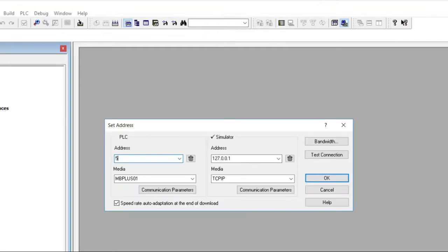If your PLC on the serial network is at node 4 or node 1 or however it is, usually your engineering workstation will take the address number 0 or 1, depending on how the addressing numbering starts on that particular serial network, and then your PLC will take 1 or 2, again depending on how the node numbers work for that particular serial connection.